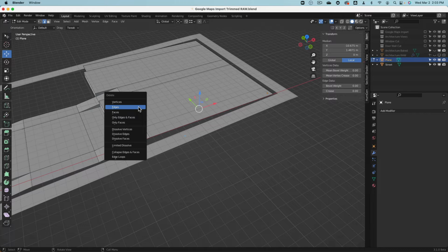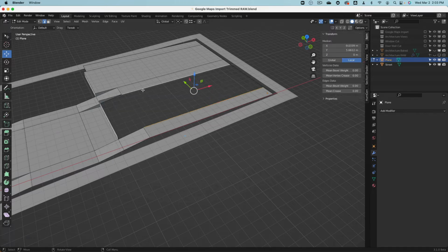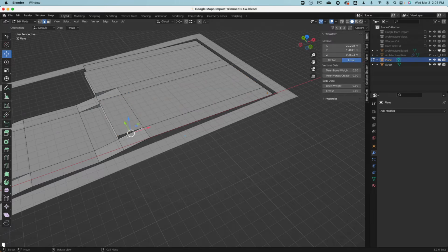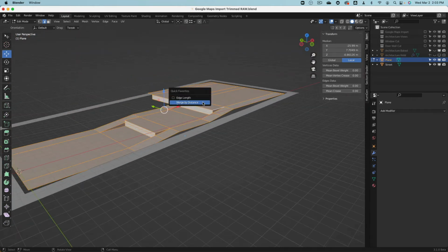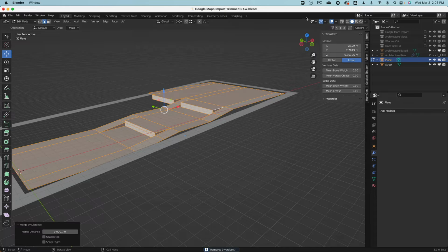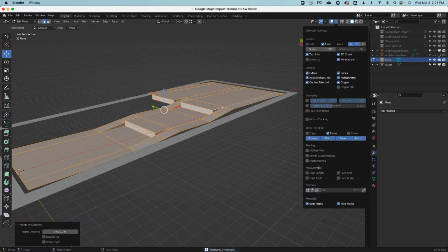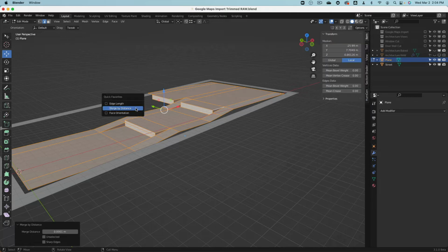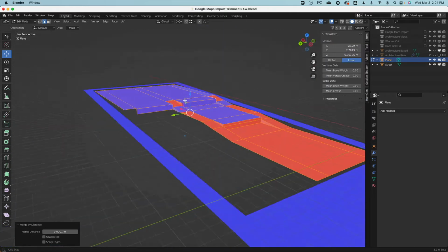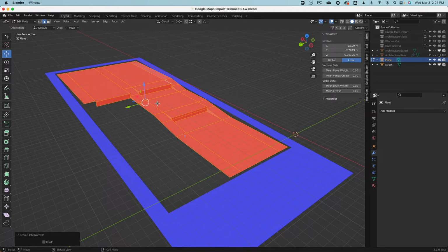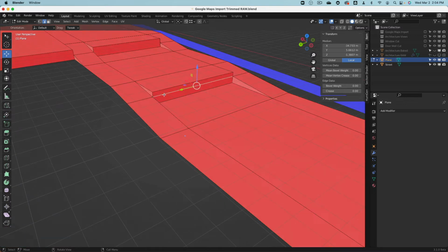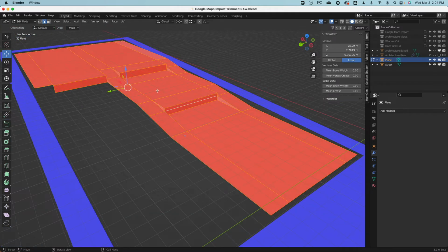I will select this long edge, delete it, and then plop, plop, and flop. Fixed. Q and oh, I don't have this put in. Right click, add to quick favorites, Q and face orientation. Ooh, yeah, that's bad. A, Shift N, and basically flip normals. There we are. Well, this is actually terrible.